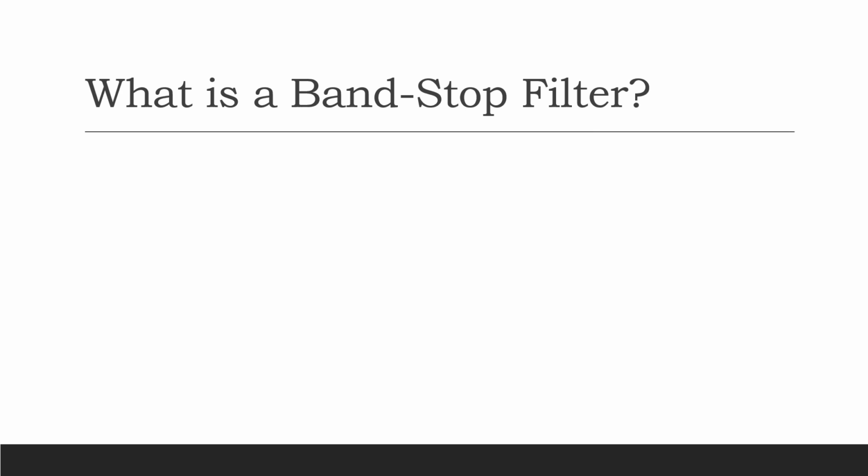Now let's talk about band stop filters. So what is a band stop filter? Well, it's a type of filter that allows high frequencies and low frequencies to go through, but it blocks just a particular band of frequencies. A frequency response for a band stop filter might look like this.